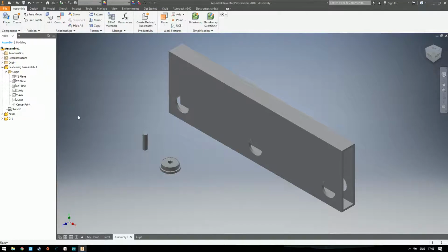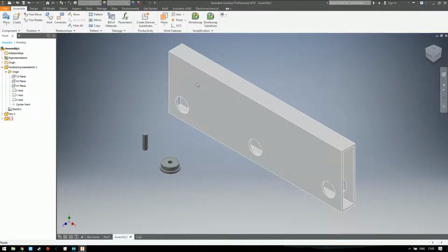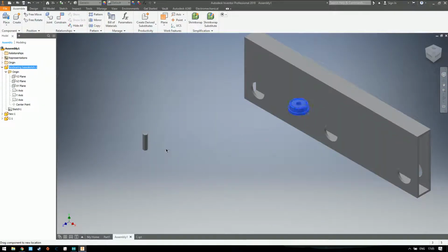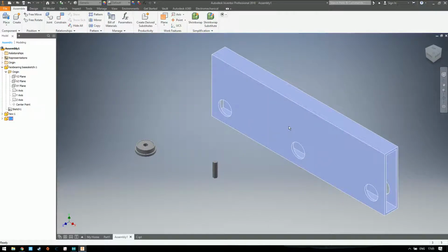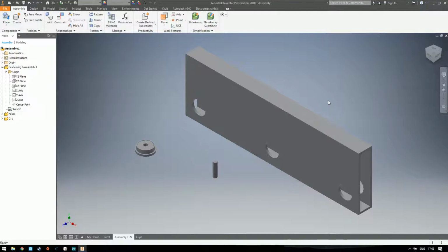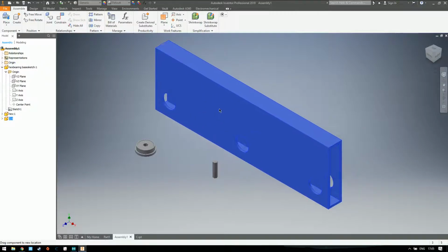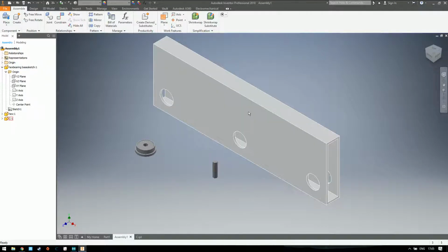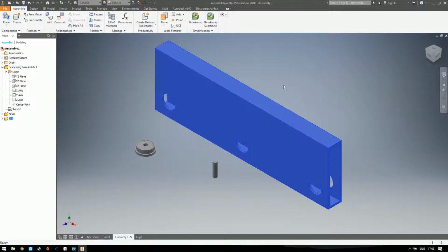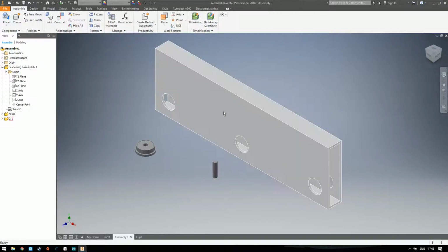Like what I said before, really important inside the assembly. Right now you have three objects that move totally free in this entire assembly. We don't want that because we need at least one thing to be the ground, the center of our entire CADing. If you want to CAD an entire robot or something, you always have to start with one piece, set that as the ground or center. Then you CAD every piece around it. I will probably show you guys later.